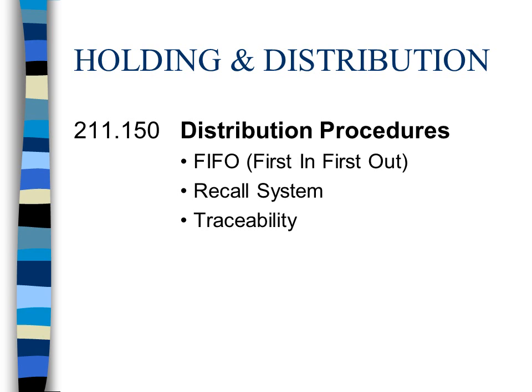Recalls mean you have to come up with all of the cylinders that have been produced from that lot or from that batch. Remember, a lot is a portion of a batch. The batch is your bulk tank. It's the big 6,000 gallon oxygen or 9,000 gallon oxygen tank at the plant.